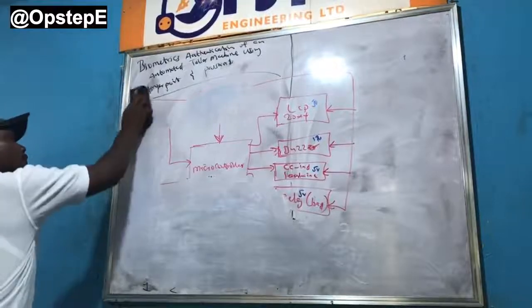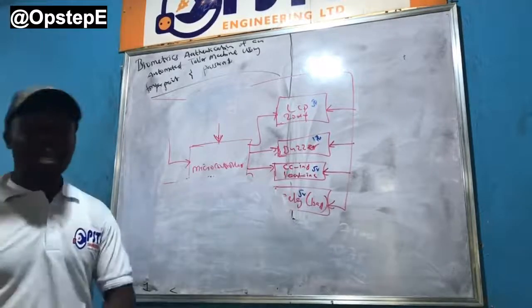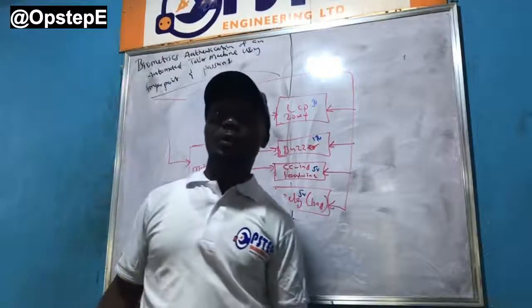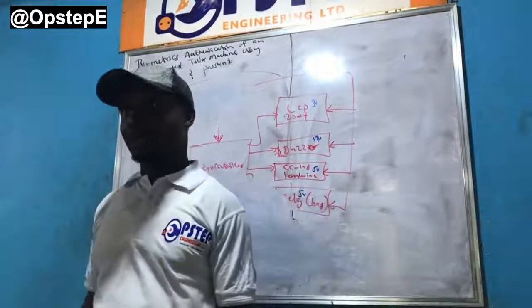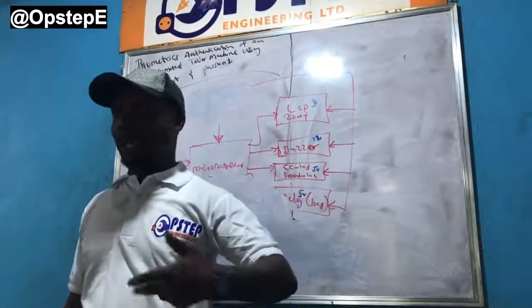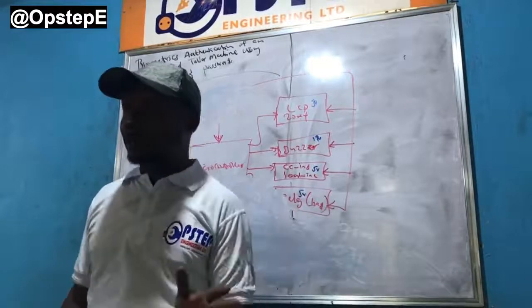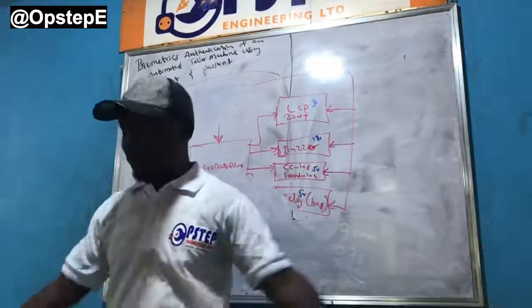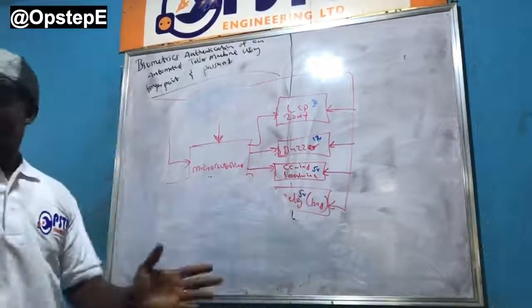So that's how the 4x4 works. Now, again, I told you guys one time when we were doing keypad, many times when I have keypad projects to do, I just make it a 4x4. Even though I might go to market and get maybe a 3x4 or 4x3 Matrix keypad, I do that. The idea is, in my header file, whatever is the KBD or C file that I get, I leave those spaces blank for the part that is not complete. So if I change my mind on the design and I get a 4x4 keypad, it still works. The PCB already is done, so it just works. So always make it 4x4.